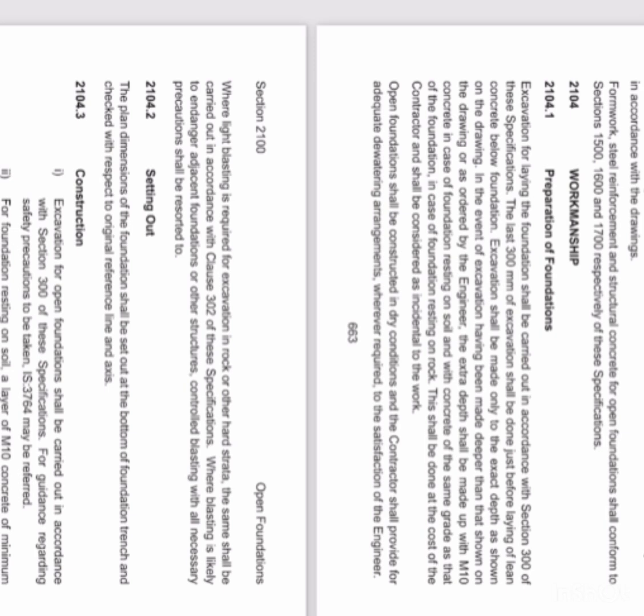Open foundations shall be constructed in dry conditions and the contractor shall provide for adequate dewatering arrangement wherever required to the satisfaction of the engineer. Where light blasting is required for excavation in rock or other hard strata, the same shall be carried out in accordance with clause 302 of the specification.